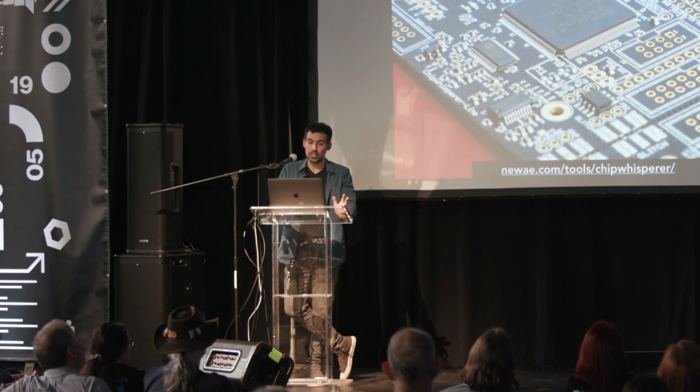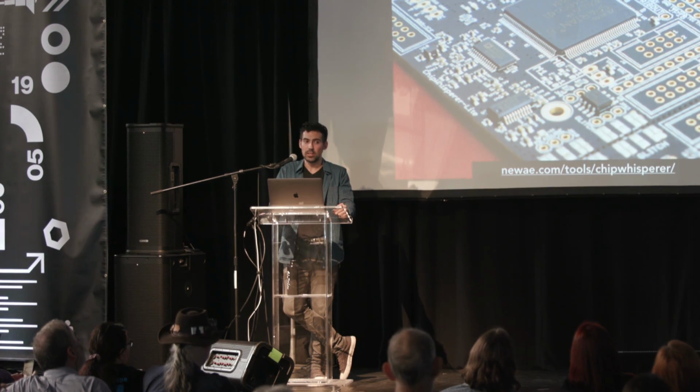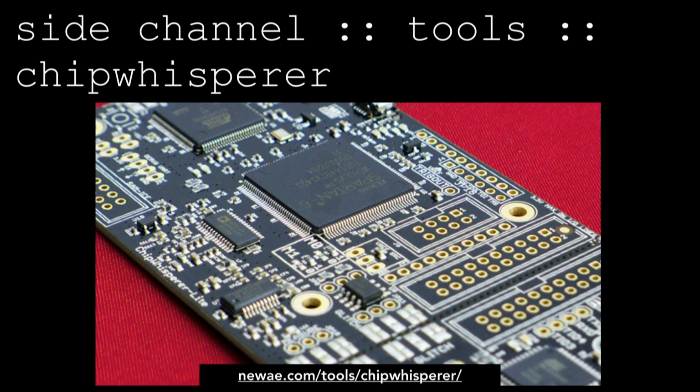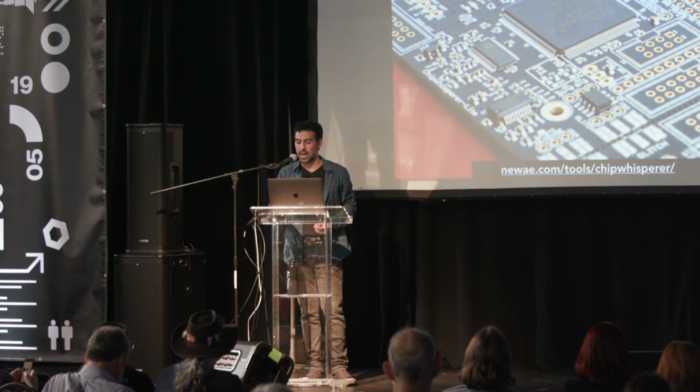Some of the tools that I would suggest that I've used: the ChipWhisperer is an amazing tool from Colin O'Flynn. It's inexpensive, has an FPGA built in, and he's created amazing videos and tutorials online, so much information that you can use to really learn how to pull off these attacks. And he's doing a great job of really explaining how a lot of these things work, as well as providing an open source tool chain, open source hardware, and open source software that you can use to perform all this stuff. And he's using real targets, which is another thing I really appreciate, grabbing actual chips that many people are using and demonstrating how you can actually perform those attacks.